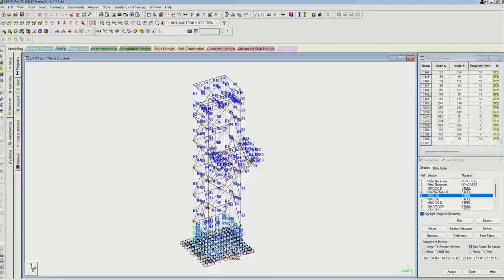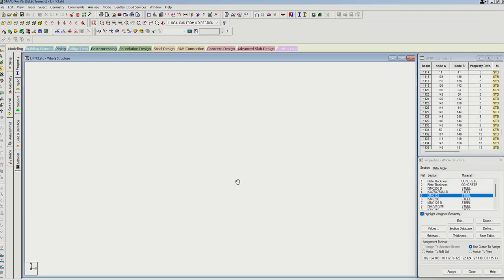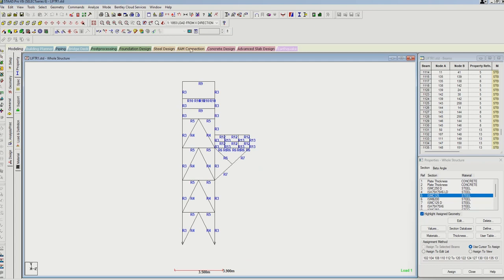So this is the lift well structure. First, we'd like to see the left part of the structure. This is the left side elevation of the structure. I would like to ascertain the dimensions. So this dimension is 2.23, 2.226, 2.226, 2.010, and we have 710 mm, 680 mm, and finally we have 1.2 meter.